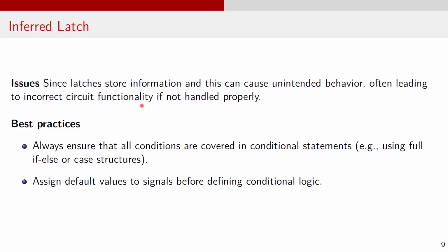Let's understand what issues can happen due to inferred latches. Since latches store information, this can cause unintended behavior, often leading to incorrect circuit functionality if not handled correctly. In a purely combinational block, inferring a latch introduces sequential behavior that may not be intended by the designer.